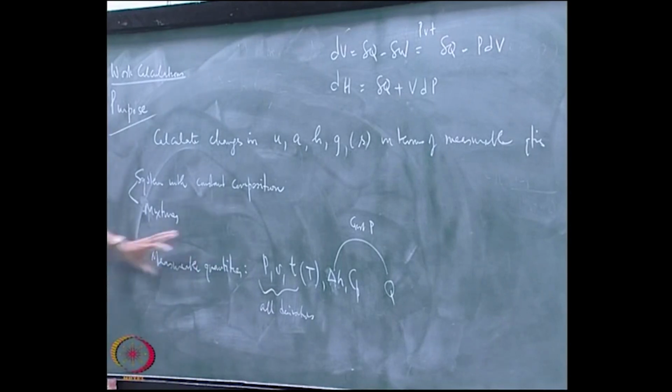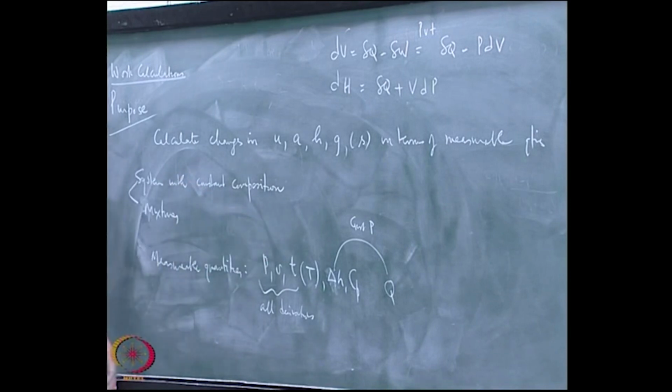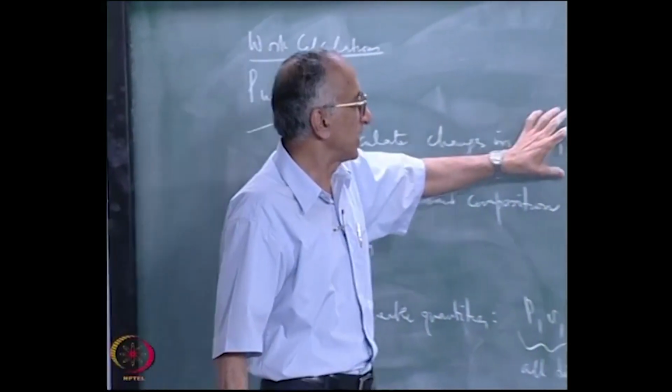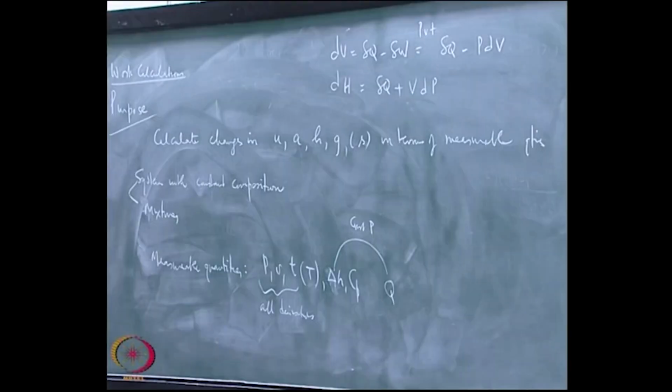All derivatives are considered measurable, although if you ask a PVT person who is actually making these measurements, it is pure hell. Making accurate measurements at low pressures, for example, is pure hell, because the volume change is negligible and to measure it accurately becomes very, very difficult. What we will do is look at only these changes, and at when you can express them in terms of PVT.